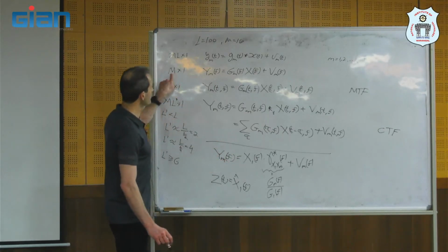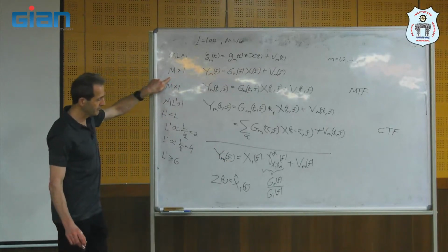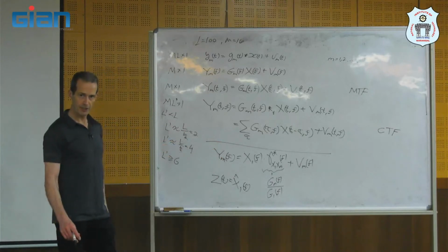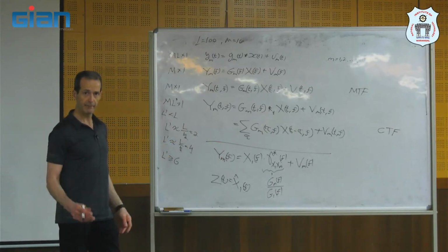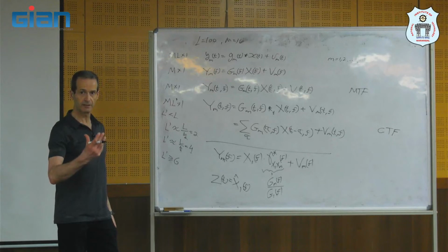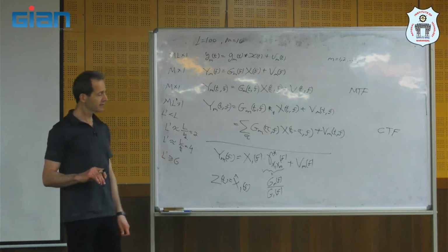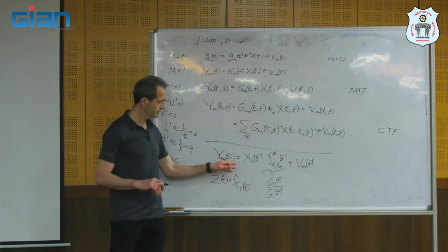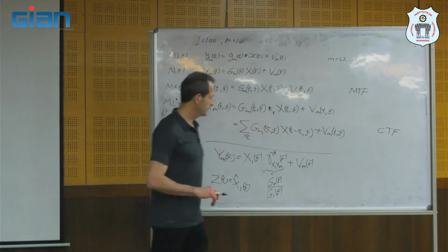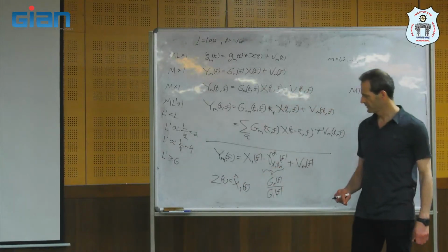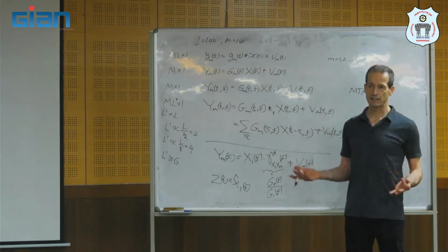So we can find a filter of length m that we apply to the m measurements for frequency f, obtained from the m sensors, and we apply the filter to these m measurements, and we get an estimate of the desired signal. This is signal enhancement.